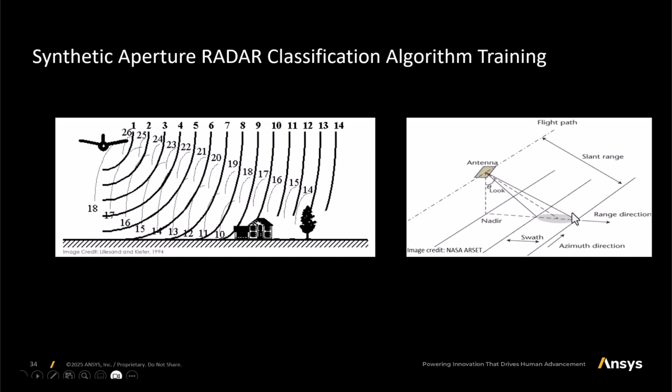The swath of the radar is nothing but the area which the beam is going to cover, so that the reflections coming back to the radar are actually the reflections from this area. Based on your swath size, your resolution changes, and the bandwidth of the radar also changes with resolution. Your look angle also sometimes matters for the resolution of the target. And your radar in this case normally moves on the platform.